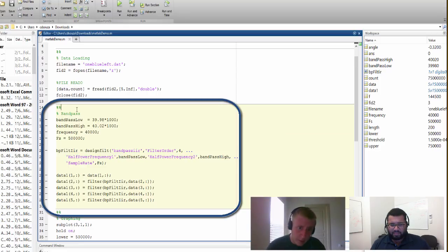What we're working with right now is a fourth order bandpass filter. This is kind of a pretty low one. It's successful in our testing. You might discover that for a more robust solution you would want a higher order bandpass filter. That's just going to be a result of your testing and what you find is best.